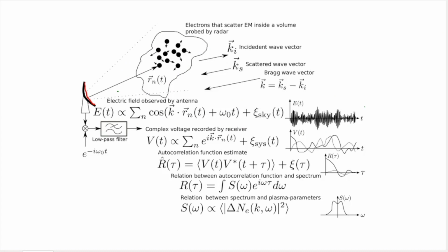Once the radio wave reaches the antenna, it propagates through a radio receiver, which amplifies the signal and filters a portion of the electromagnetic spectrum where the radio signal of interest resides. During this process, more noise is added to the signal due to losses in the radio receiver components. The primary sources of noise are the first stage preamplifier of the radio receiver and the transmit-receive switch. The radio receiver also performs a frequency shift operation and filtering operation, which is called complex baseband conversion.